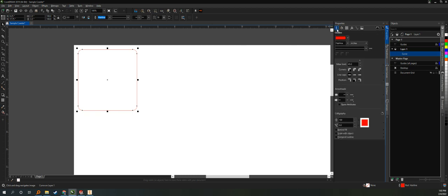You'll see a pen tool and you'll see a paint tool. A paint tool will be any sort of object fill. The pen tool will be an outline. I can make this outline have a thickness, and I can also make it have no thickness. So there's no outline. The object's still there, but there's no outline on it. What we're always going to be doing is a hairline. That means just one single vector line the laser can read as a path to trace with as a tool path.